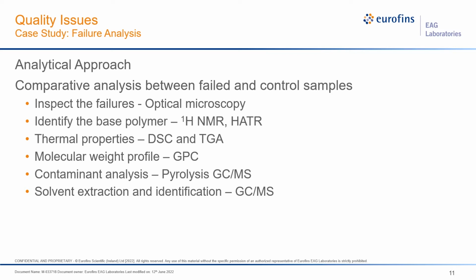The thermal properties helped in further identification of the base polymer and the respective thermal profiles given off by the materials. Because the polymer had been correctly identified in the previous step, the thermal profiles could be looked up and compared to what was obtained experimentally. The thermal properties did match up to the composition of the base polymer.